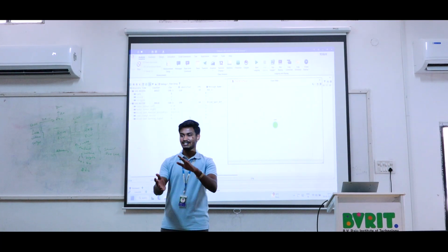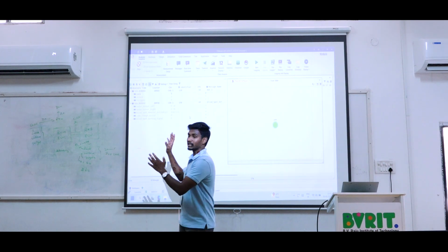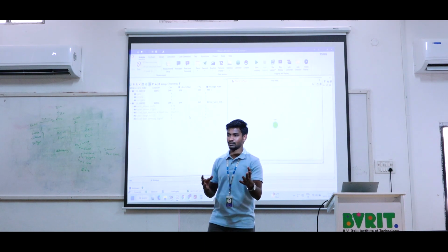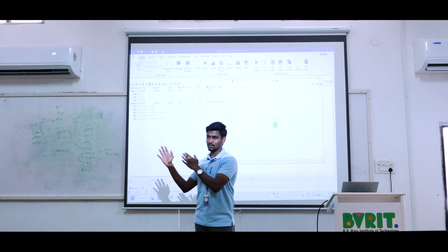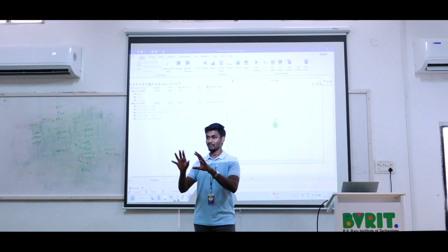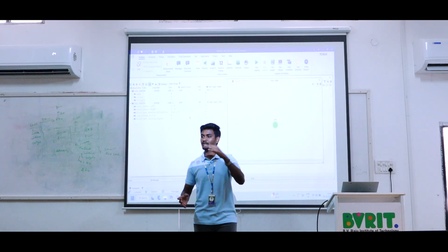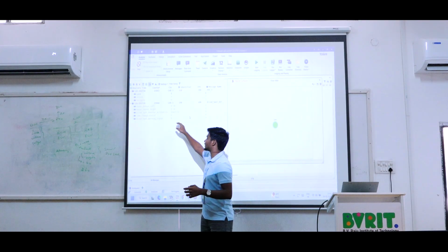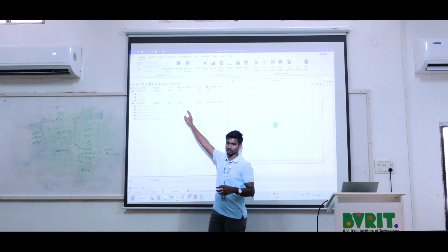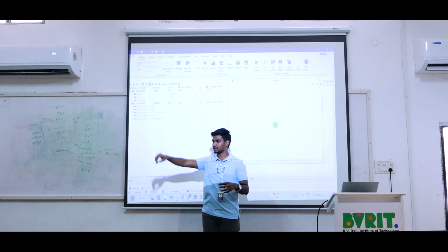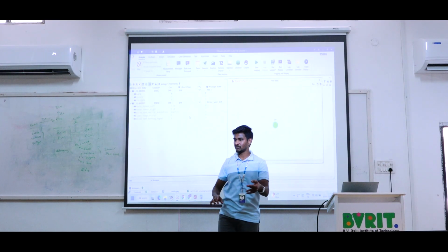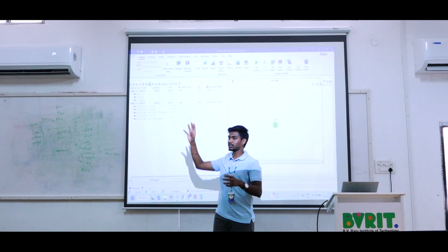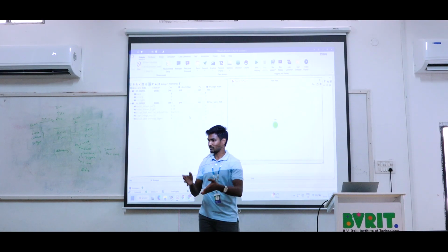As a clarification, the CAN frame format is working on the back end, so we are not able to see the start of frame, acknowledgement, error and CRC. I don't have any front end output for that. It works on the back end, but whenever we find an error, you will get the red color output traces here. That I will also show you. You are asking about active error and passive error; I have a statistics window for that, and I will definitely explain it.